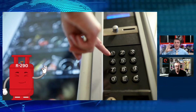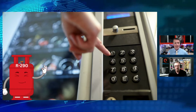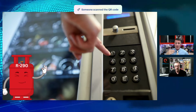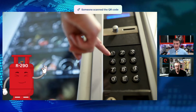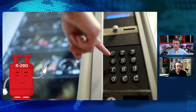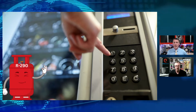So this is going to be refrigerants for newly manufactured equipment, but that doesn't mean that's not already out there. That just means that all new equipment is going to have either A2L or it's going to be an A3 design, right? In these applications. And remember, there's a big difference there. A2Ls are mildly or slightly flammable, and A3s are highly flammable. Highly flammable. That means you're not going to be using the same manifold gauges working.